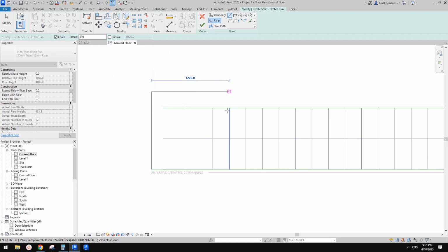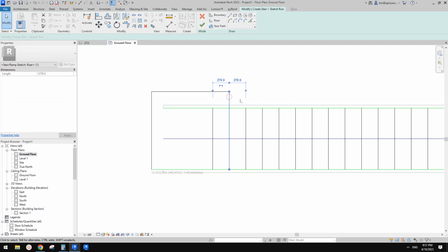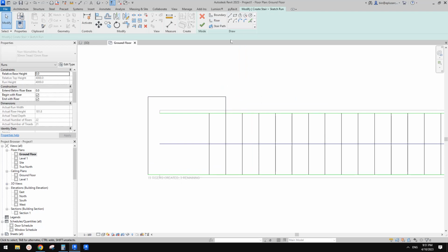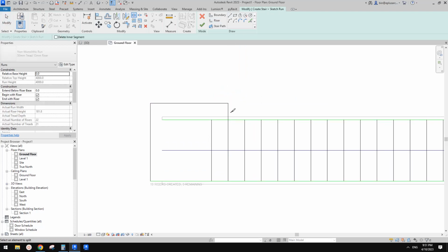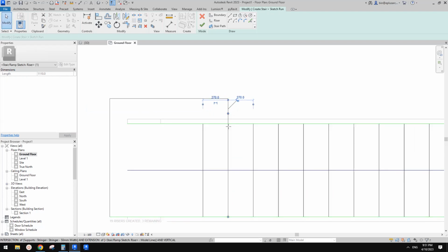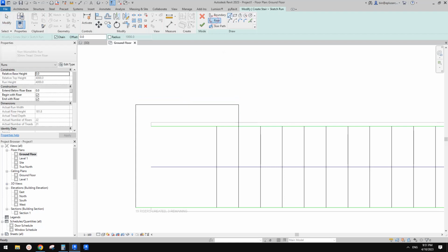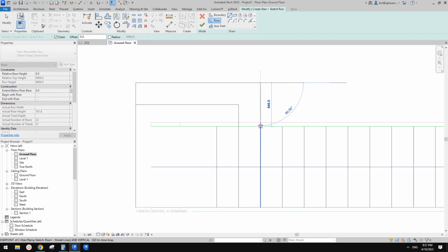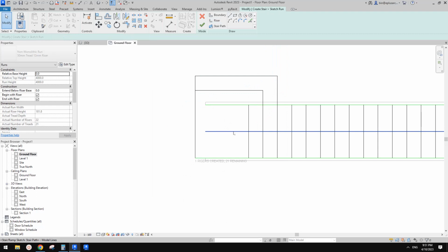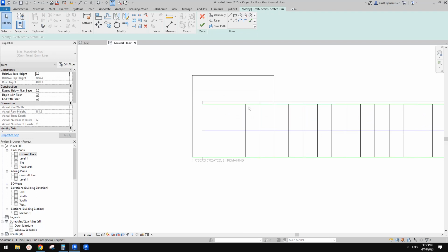I'll just press shift, so I can just align with that line. Oh, interesting, it's automatically trimmed. So that's not what we need. I'll just split it, SL split, and then just go down. Okay, riser again, so go up to 70 again, go down with shift. I'll just put it here, and then come down here.